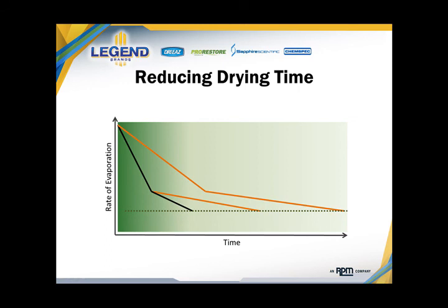In other words, for the best overall drying time, initially, we must focus on a very high velocity of airflow over every wet surface in the building. Then, as we transition into free and bound water, we must begin to move our focus to a low humidity in the drying environment along wet surfaces and ensure that all building materials have an adequate internal temperature.